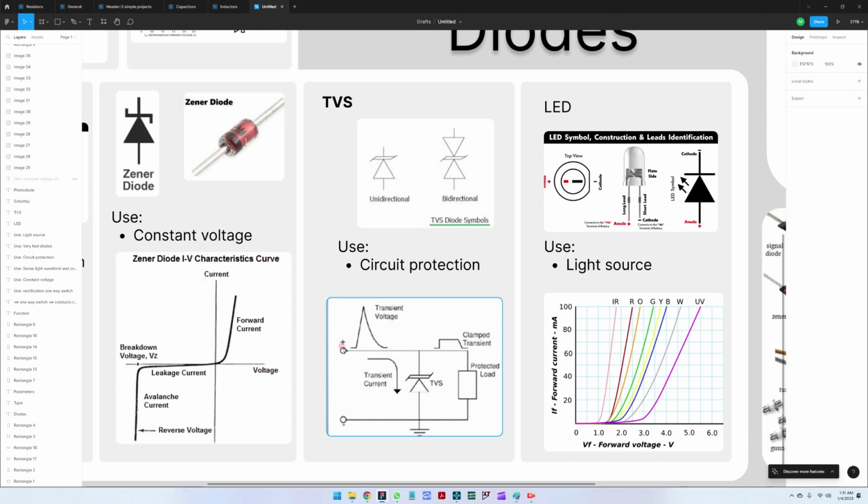You can see it here. So the voltage rises, and when it exceeds the TVS diode's designed limiting voltage, it will automatically short it to ground. And you can see this is the input waveform where you have a very high spike, and this is the clamped value. So you can see the same spike, but the top side, the high voltage here, will be totally cut off, and then would protect the load.